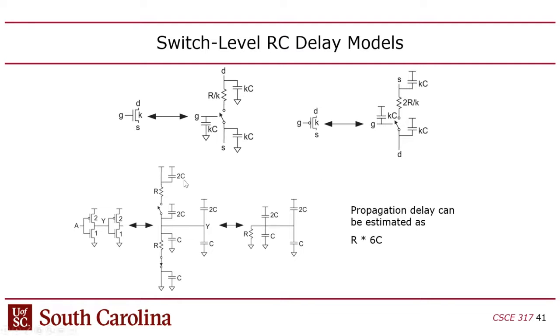Also notice the reason these are 2s is that we're assuming the pull up is size 2. I just noticed a bug. No, that's right, this is still R because it's 2. Sorry, scratch that. The PMOSs are 2C, but only 1 R for the resistance, because you have to double the size of the PMOS in order to get 1 R unit of resistance.